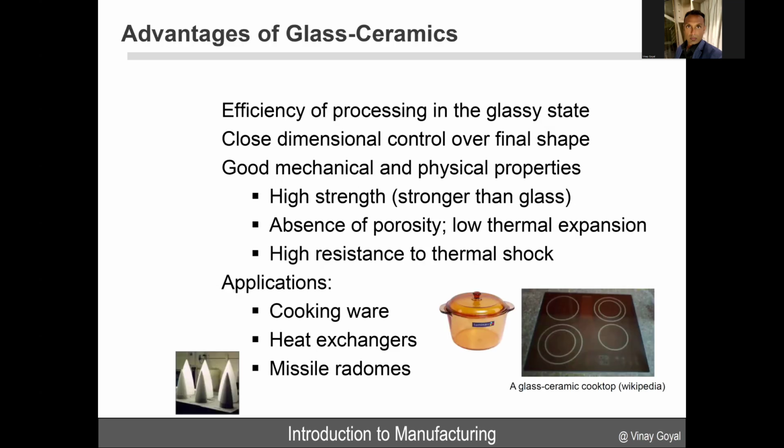What is the advantage of glass ceramics? They have efficiencies in processing into that glassy state. You can get better dimensional control over the final shape. They have great mechanical and physical properties like high strength, and there's an absence of porosity, so as a consequence there's low thermal expansion and high resistance to thermal shock. That's why you'll see them a lot in cookware, heat exchangers, and some radomes.